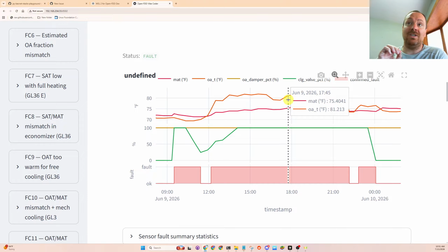And I think we know this already, that in the previous videos we plotted the outside air temperature sensor reads higher than the mixing air temperature. But what is kind of odd here is that, for one thing, we see this mismatch, but another thing is that this could be a really big mechanical waste of energy going on here.